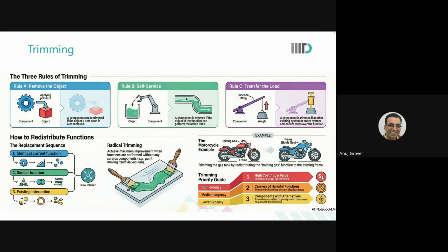We had the idea of a spring on which the tank would sit, and as the weight of the tank increases, the spring would press. We also had an idea of a pneumatic mechanism, where as the level of paint rises in the capillaries, it would compress the air or gas inside the capillary, and that would activate the switch. Are you with me? You remember?